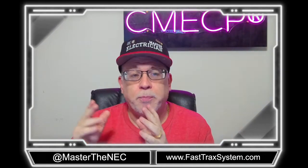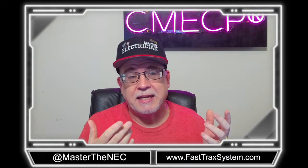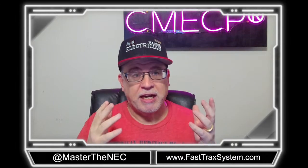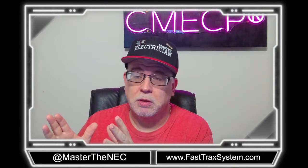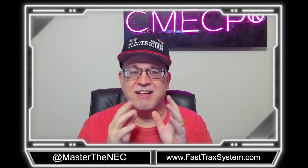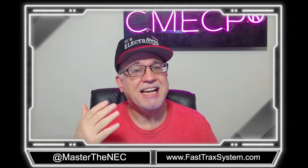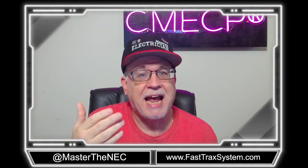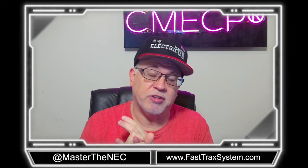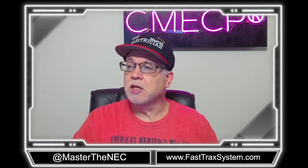If I do use a portable generator to supply power to a dwelling, then I want to make sure that if it is a bonded generator, I have a transfer switch that switches the neutral. If I'm using a floating neutral generator, then it's okay for me to have a transfer switch that is solidly connected, not switching the neutral. But again, you only want to use the floating ones on a premise application, because we just saw what happens if you use it as a standalone. The GFCIs won't function, and the overcurrent device likely won't function, so that becomes a safety hazard as well.